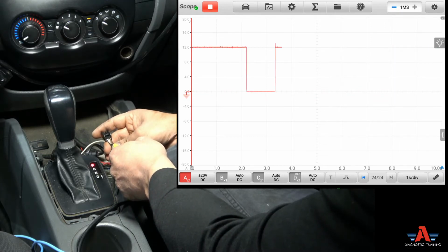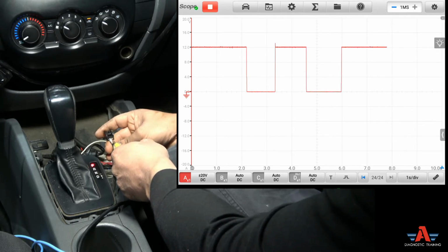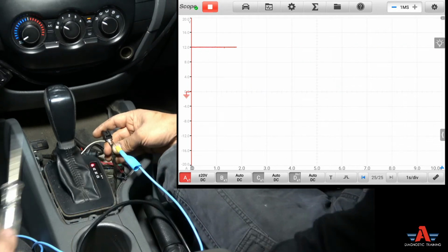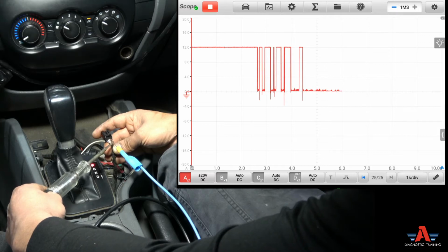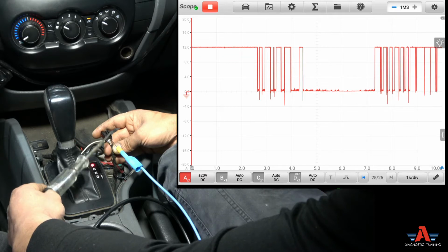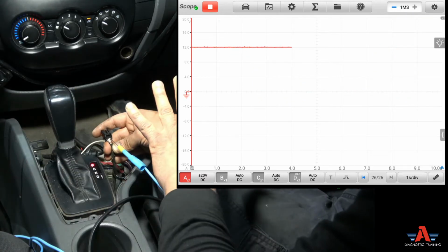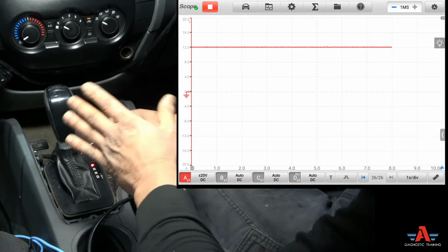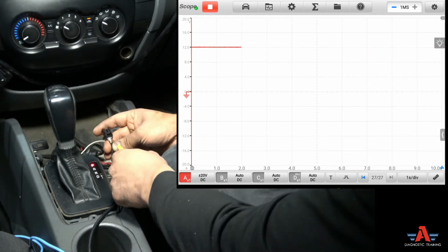And every time I touch it, you can see on that white with the blue wire, that's a 12 volt reference, because our test light is not lighting up. If I drop that voltage down to 0, you can see on the scope, and the test light is not lighting up. That's 100% coming from the computer, bias voltage. Guys, every time I get mixed up bias and reference, but you know what I mean, it's a bias voltage, right?